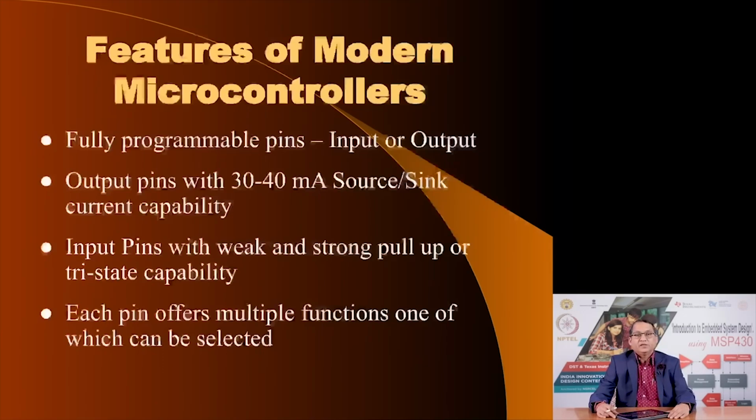What if I need the total number of input and output pins to be 12, but I want 10 inputs and 2 outputs, or 10 outputs and 2 inputs? Now, in principle, this 18-pin or 20-pin IC is quite capable of satisfying the requirement, but if the inputs and outputs are equally partitioned and fixed, then this specific application where I need 10 input pins and 2 output pins will not be able to use such a microcontroller.